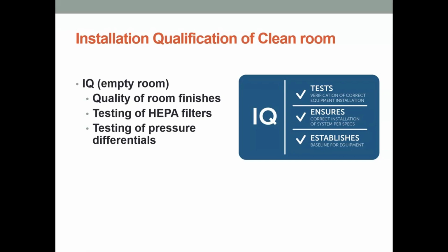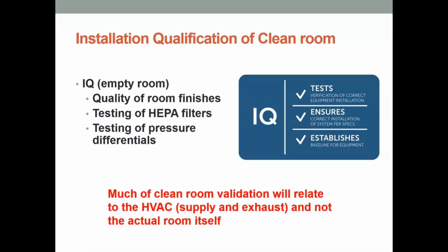We're going to be looking at the testing of the HEPA filters to make sure that they're operating. They would be extremely critical in a clean room. Testing of the differential pressures, which again prevents particulates, contaminants from entering into the room as well.